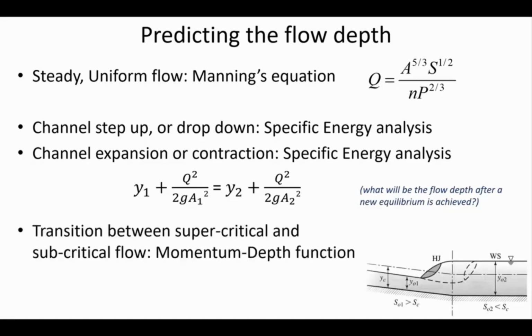Okay, next, here in chapter 13, we're going to look at a different type of non-uniform flow. Just as an illustration, what this figure is showing is what if we had two different channel slopes coming together. We had a steep section of a channel that matched into a relatively shallow channel section. In this steep section, it was steep enough that the flow is going supercritical. And so the Froude number is greater than 1 when it's supercritical flow.